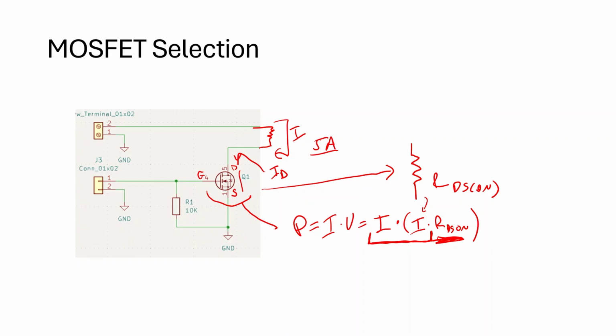So this is a calculation you can do, right? Don't just arbitrarily decide, oh, Colin said use a really high current, so I'm going to use a really high current. There's a pretty quick calculation. The datasheet's going to also have a spec for how much power gets dissipated and how hot the part gets, which will be based on some rough assumed PCB. But all of this you can do very ballparky type calculations on.